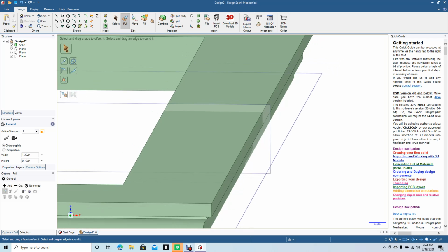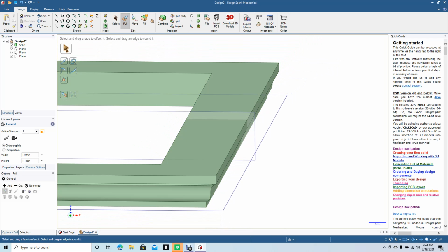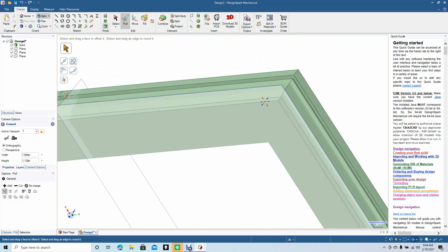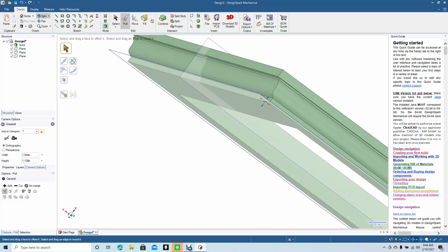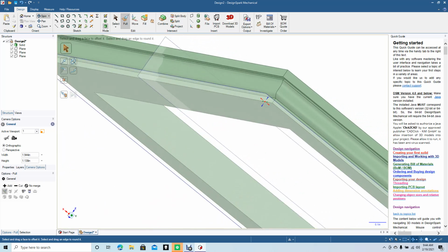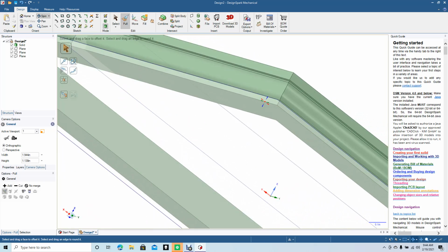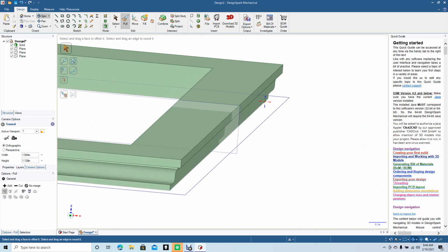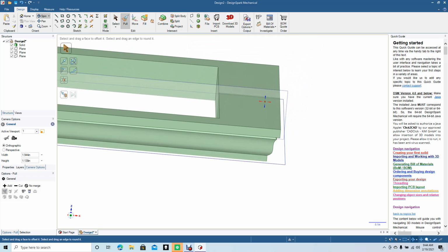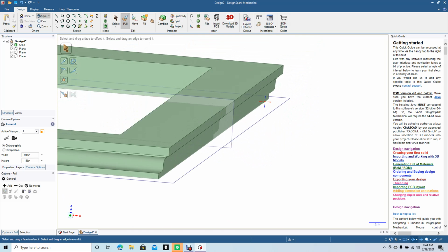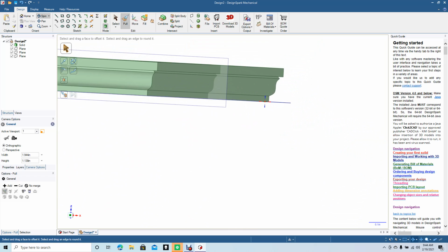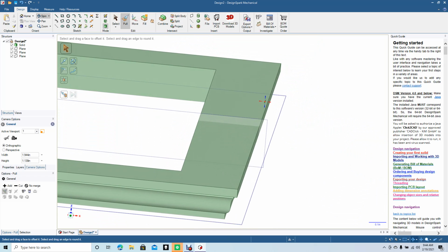Okay, so Control minus, hit the spin tool, take a look at that. So that's basically our window shape. And this is a really useful feature. This would be a shape that a router could create. So if you wanted to create a small window frame, maybe to put something in, you'd use this feature, the sweep feature.